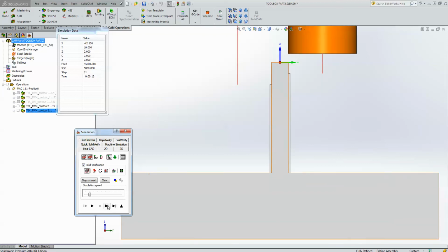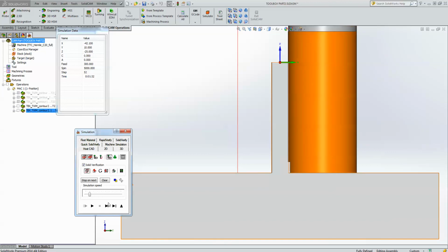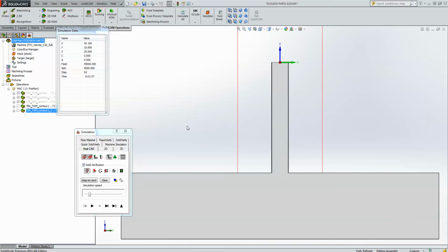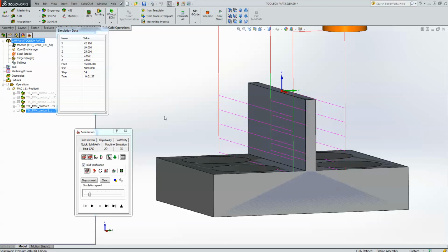Now, as it goes down to this side, now it's going to go down 5 millimeters from here. When it does that, again, it cleared for 5 millimeters of material over here, but it had this amount of support on the other side as well. And that works all the way down to the very bottom up until it gets to the floor. Once it gets to the floor, after that 5 millimeters, it has 2.5 millimeters on the very bottom on the other side to clear away. And that finishes off that entire wall over there. That's actually probably the best way to work on thin walls. And this is done now all in a very simple operation.